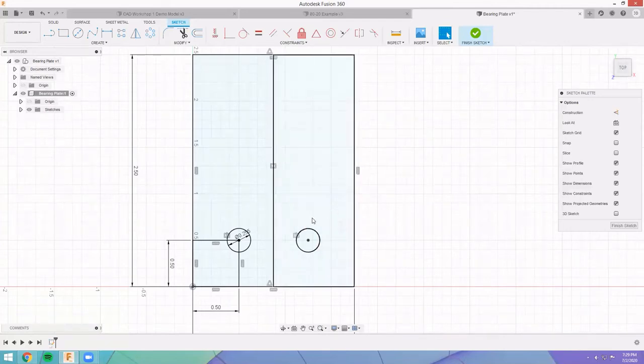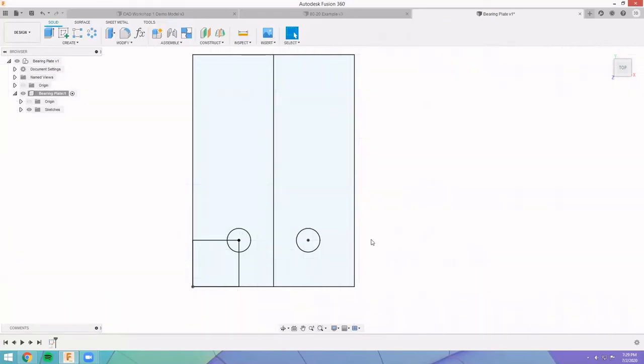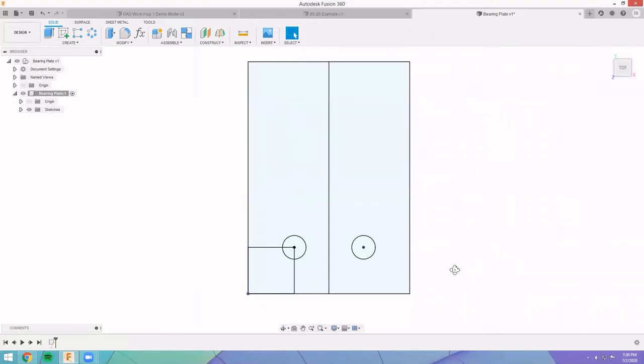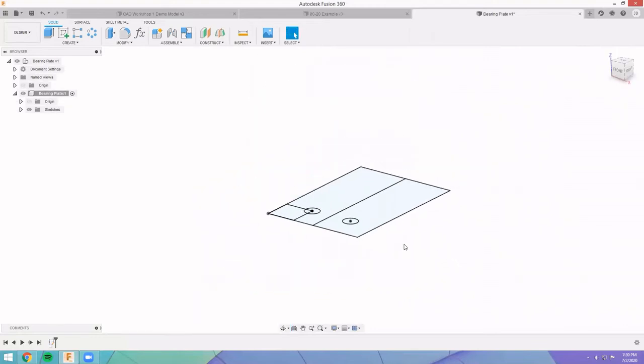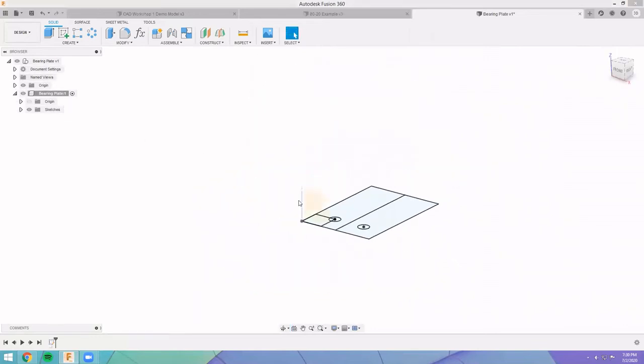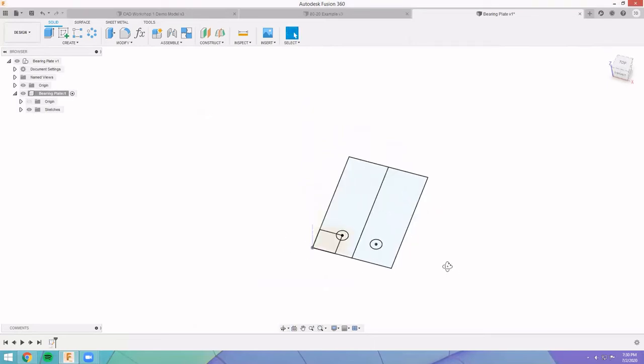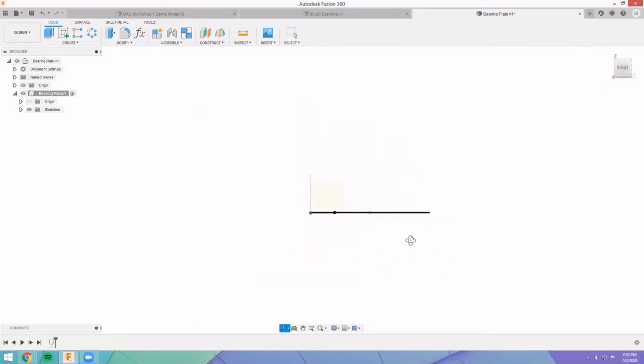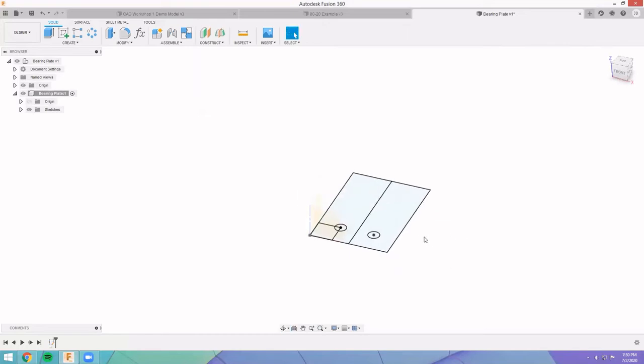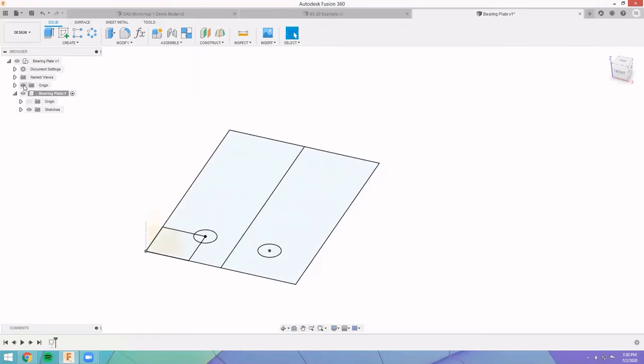And we're going to go ahead and stop our sketch here for now because we're ready to make a 3D shape. So we'll click Finish Sketch. Now, just to prove what happened, that sketch basically exists right at XY0 and is 2-dimensional. So it's got no thickness this way and is just like an imaginary drawing.